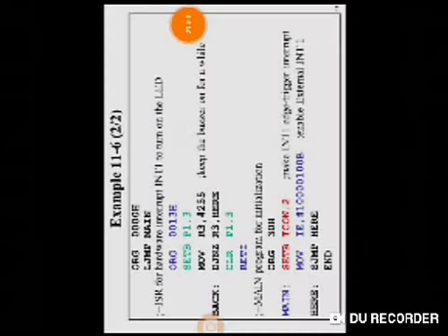In a similar way, we can also write the interrupt service routine for the timer overflow, as well as the serial communication, as well as INT0. All these we can write with a similar program. The only thing is that you need to first write the program at the respective service routine, and separate your main program somewhere else, and set the interrupt priorities, or the interrupt enable type, as well as the interrupt control.